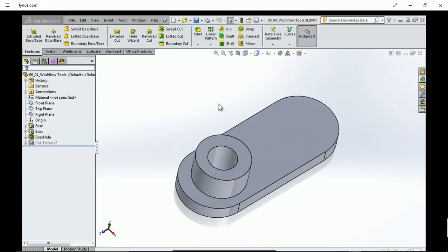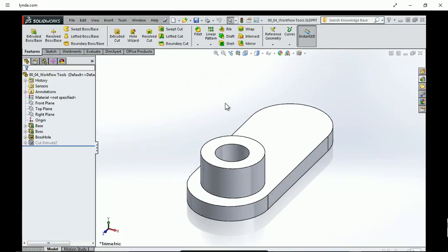Now, Solidworks has a user-friendly interface, and the developers strive to bring the required modeling commands, figuratively speaking, to our fingertips for speedy access. The first useful tool I mostly use is mouse gestures. This tool can be activated by clicking the right mouse button in the graphics view area and moving the mouse slightly in any direction. Once activated, we are presented with a wheel populated with common commands relevant to the edit mode I'm in. The commands and location of the commands on the wheel can be customized with our preferred commands and their location.